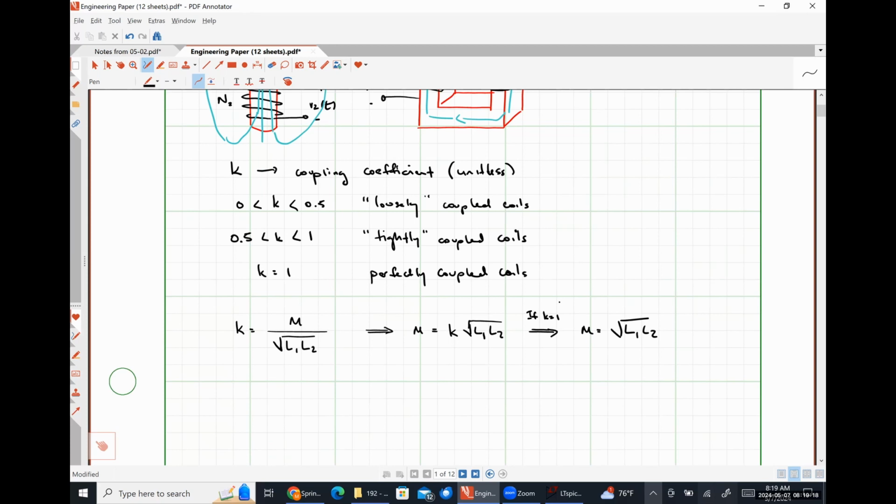So it depends on whether it has a single coil or two coils. If it is a single coil, that is what's known as a toroidal inductor. If it has multiple coils, meaning you have two or more sets of wires leading out, because we can definitely have transformers with multiple outputs, those would be considered transformers. You are required to have at least two coils in order for it to be a transformer because it needs to have magnetic coupling between the coils.